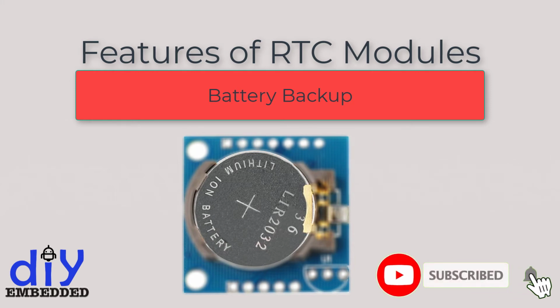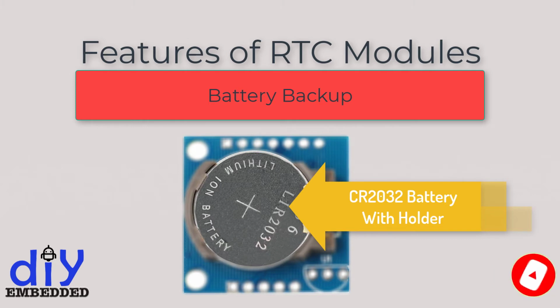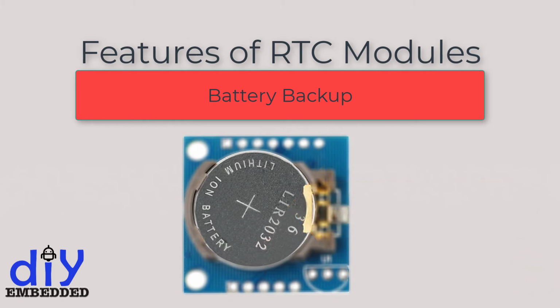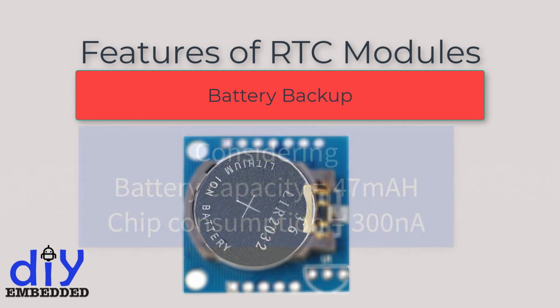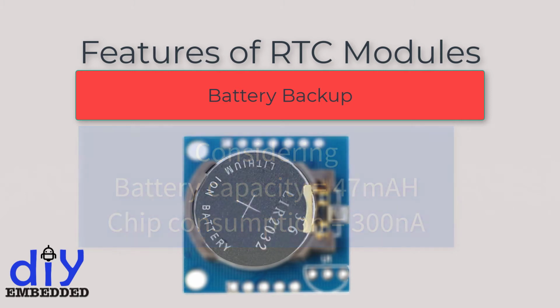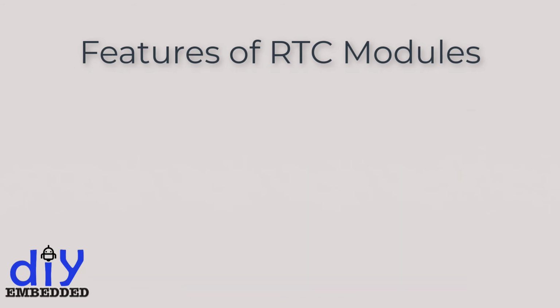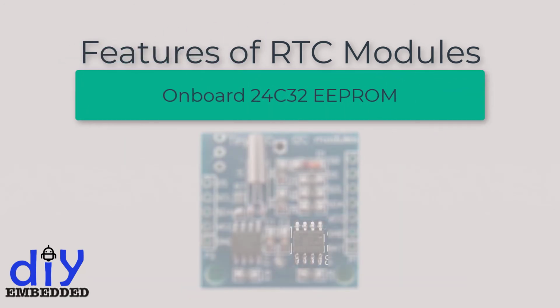The bottom side of the board holds a battery holder for 20mm, 3V lithium coin cells. Any CR2032 battery can fit well. Please note, assuming a fully charged CR2032 battery with capacity 47 mAh is used, and the chip consumes a minimum of 300 nanoampere, the battery can keep the RTC running for a minimum of around 17 years, without an external 5-volt power supply.